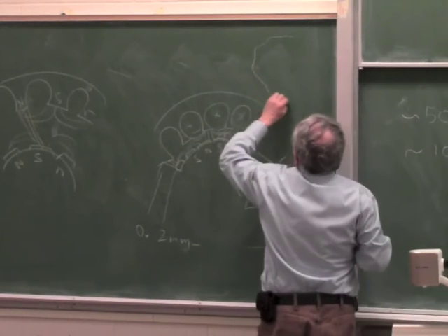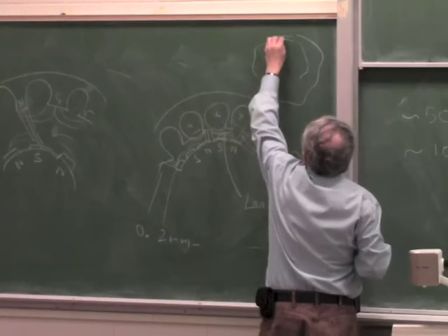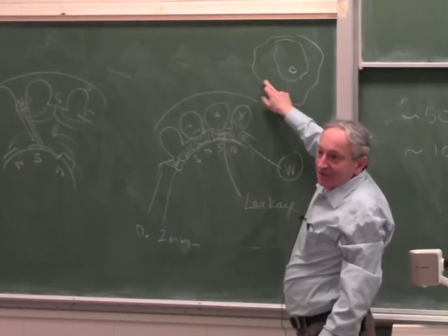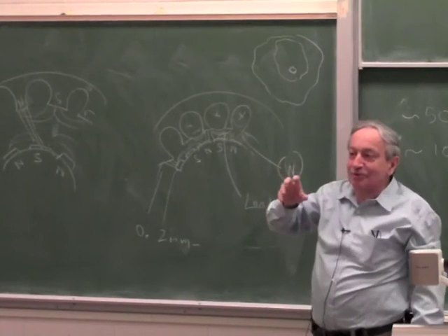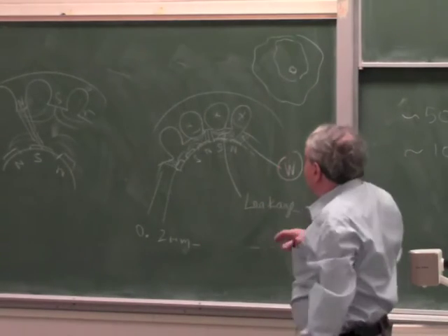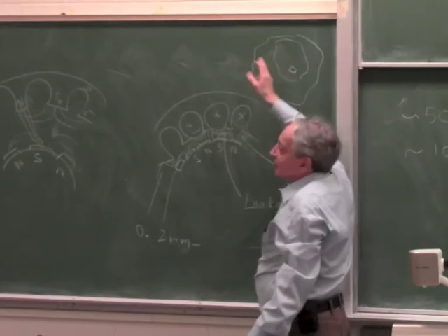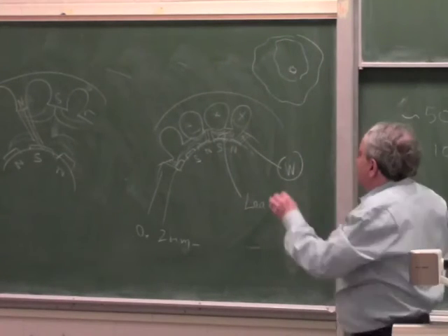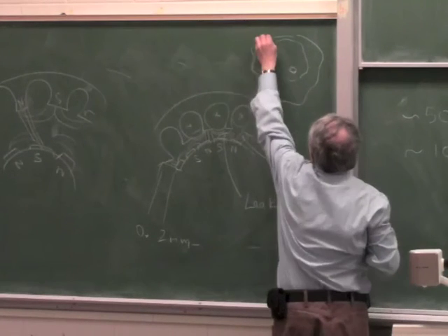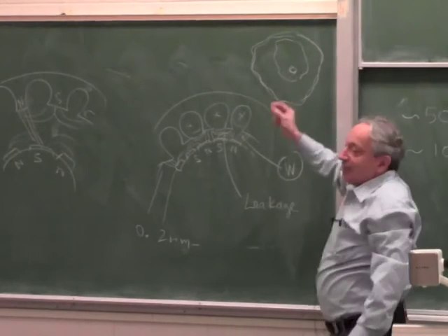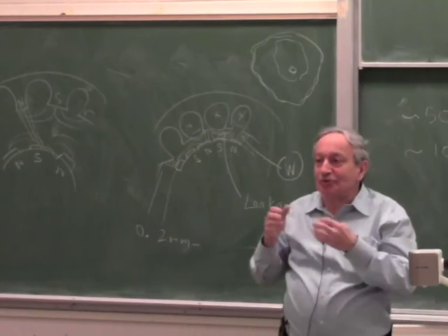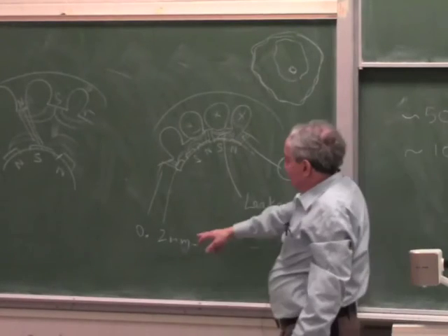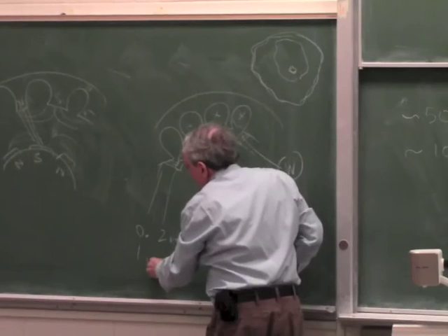So imagine you have some rough stator, exaggerated, and a slightly eccentric rotor. At some point the rotor will come closer to the stator, so the torque will not be constant, and the motor will make funny noises. So they increase the gap, not just because they don't want it to touch, they want the field to be more or less uniform. Right? So if the variations here are 50 micron, which is typical, you can't make the gap 100 micron, because the flux will change 2 to 1 depending on runout. Okay? So that's why for small motors that's typical, for big motors it's typically 1 millimeter.